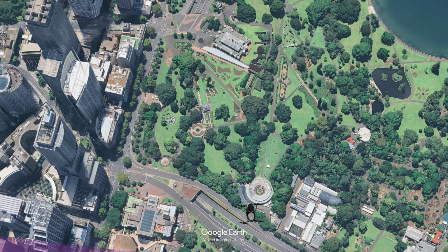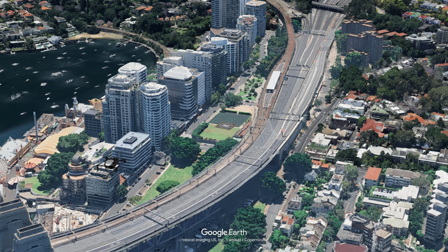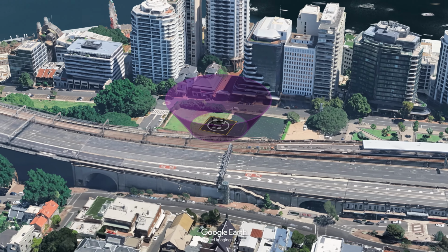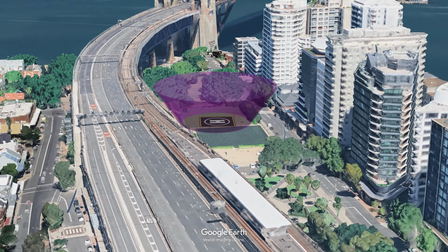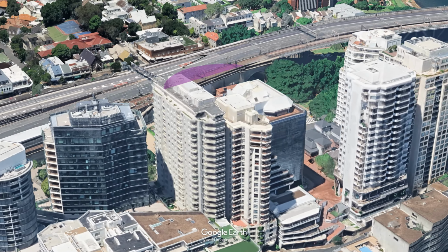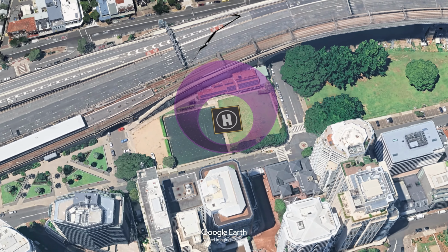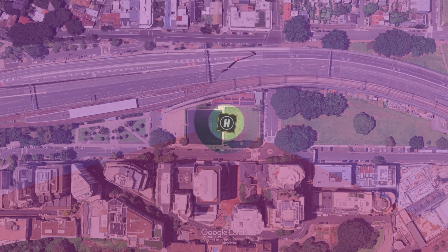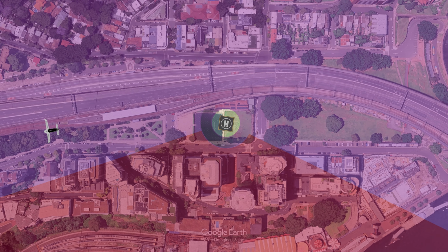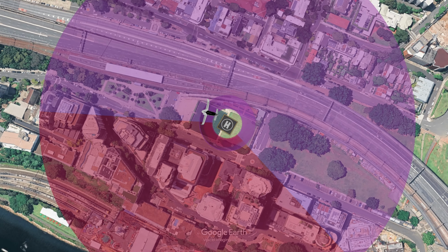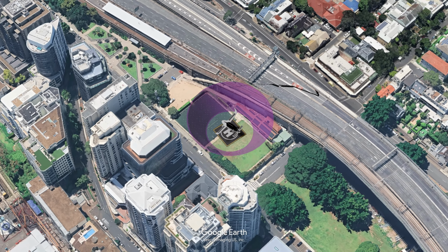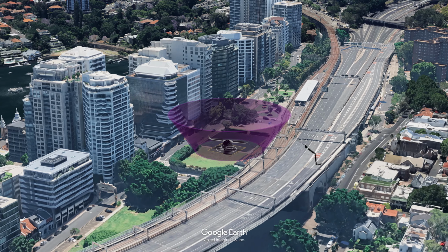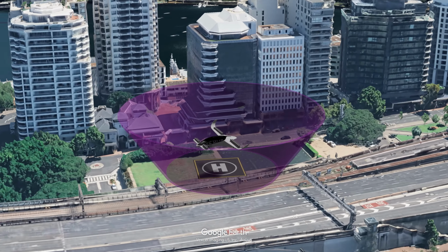The omnidirectional procedure volume, which is slightly more complex, is designed for a vertiport that allows for approach and departure routes from multiple directions. This is likely to be used in busier vertiports, where multiple approach paths are necessary. However, even in omnidirectional volumes, certain areas may be blocked. In such cases, the volume is not truly omnidirectional in practice, but adapted to the specific conditions of the vertiport. To go from the procedure volume to the full obstacle-free volume, a safety margin is added around the entire procedure space. This ensures a buffer between the aircraft's route and any potential obstacles.